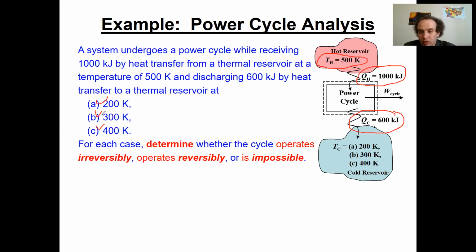So what are you doing? What is your strategy? Now please be careful, you employ this strategy for practically all problems we have. First of all, you say, okay, what is my work output? By the way, it's not known here. From here, you will say that your work will be 1000 minus 600, correct? So it will be 400 kilojoules. You get it from here.